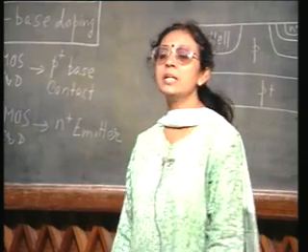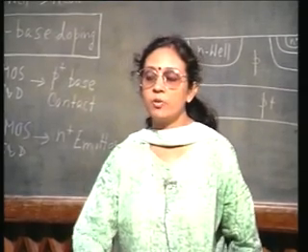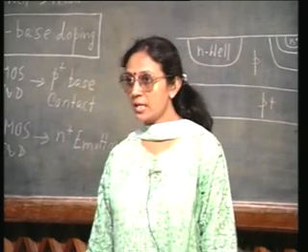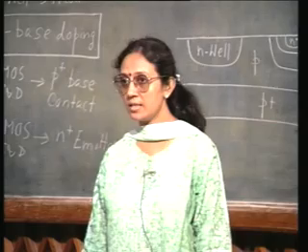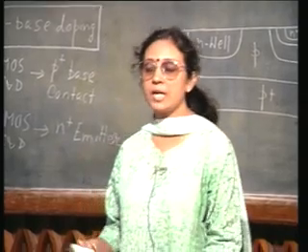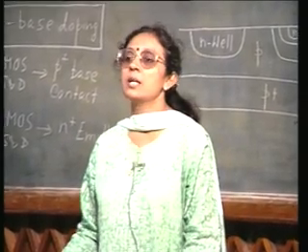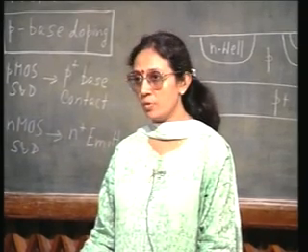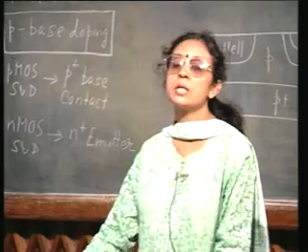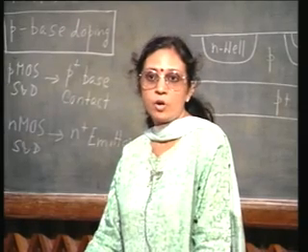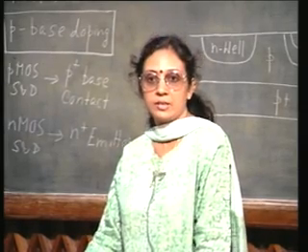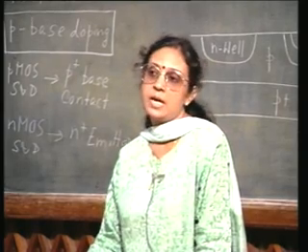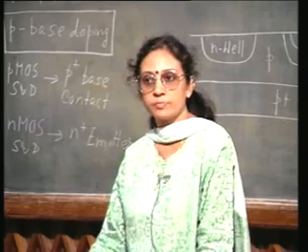That will surely enhance the performance of the bipolar junction transistor, because of the N plus buried layer to reduce the collector resistance. At the same time, this will create less likelihood of the latch up problem for CMOS. So, we are trying to use this buried layer for mutual advantage, the advantage of bipolar junction transistor as well as advantage to CMOS.